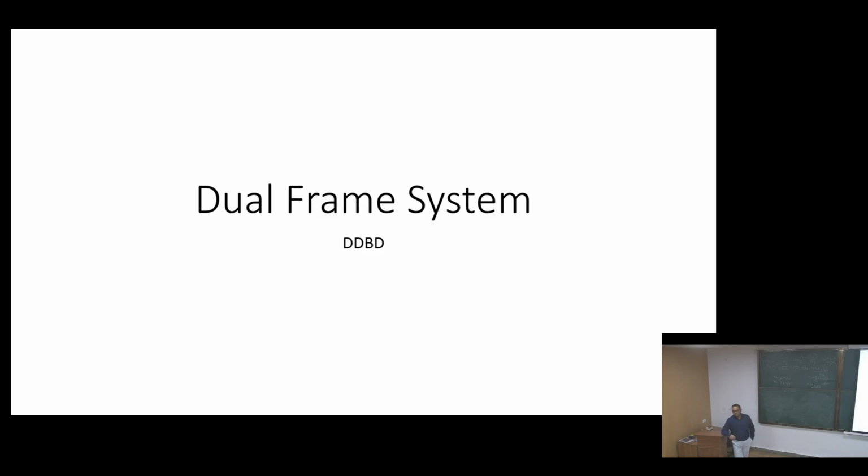Shear walls plus frame. So generally that's what the majority of the buildings are made of, especially high rises. There's a shear wall system, which is your main lateral force resisting system, and then there's your gravity system, which is the frames. And they interact in very different ways, depending on the material. If it's a reinforced concrete structure, the interaction is different. If it's a timber structure, the interaction is different. If it's a steel structure, the interaction is different.